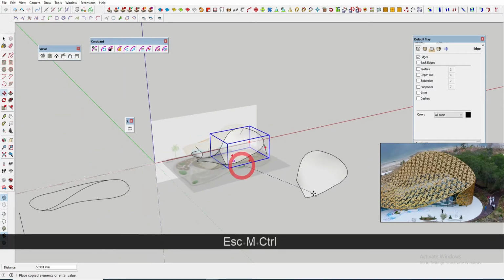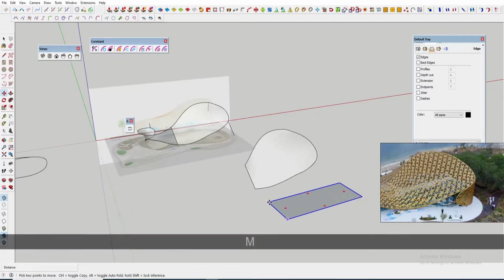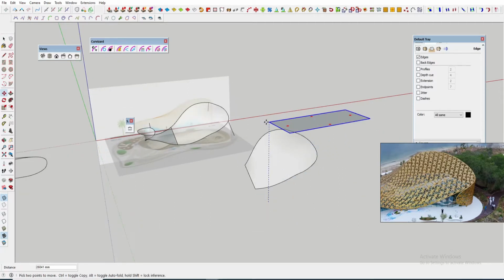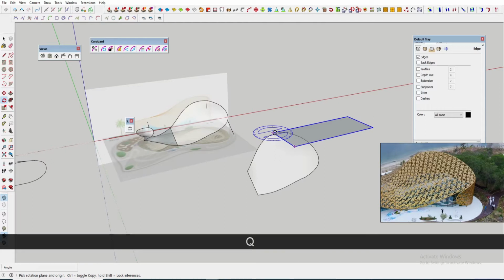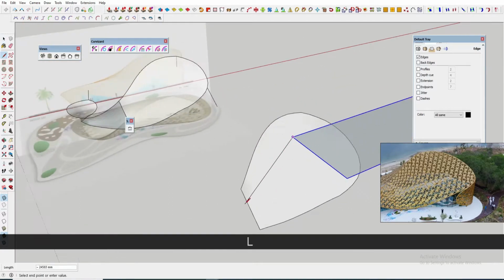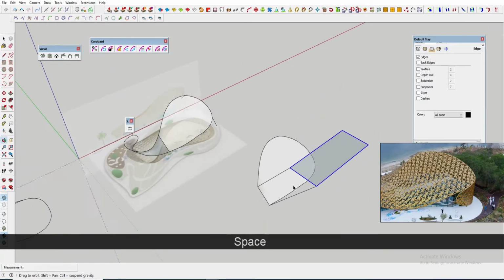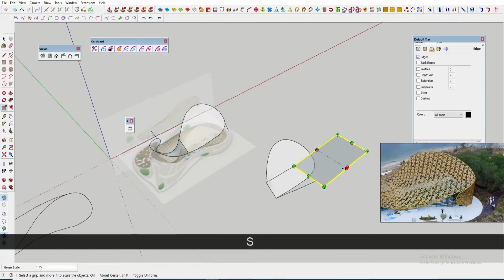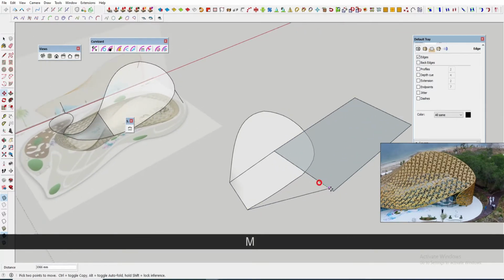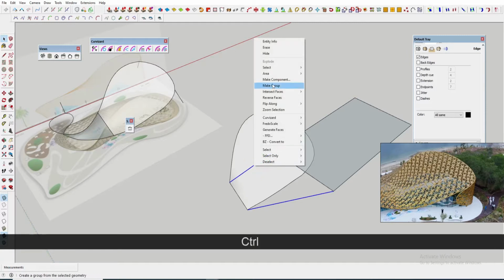So I'm going to create a pattern using the Flowify plugin. For the Flowify plugin, we first need to make the projection plane, the target surface, and the projection lines. These 3 have to be separate groups, and then we need to put all 3 together as a separate group.